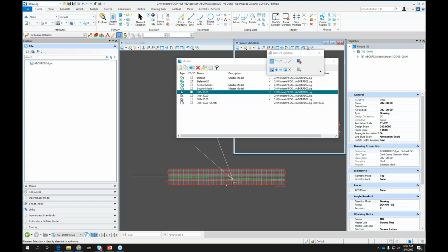How to show a borehole in the next even station on a cross section. Right, again, the boreholes do not project to a cross section the way you could have them project with the old Geopack tools. It has to be true. So you could either create cross sections at those odd intervals and show the boring logs, or, if you needed to, you could just rely on the soil survey sheets and have all of the lithology for each of the boreholes already placed there.